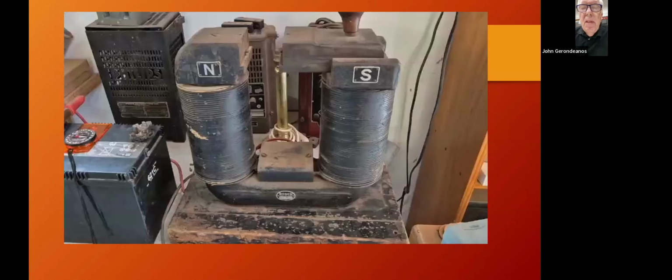And then the maximum amount of turns you can get on there with the thinnest amount of wire will build your best magnetizer. So the key steps to plan are, obviously, we define the requirements and we calculate the magnetomotive force. We're not going to do that. We're just going to take examples from real life, but if you wanted to, this is what you do. Calculate the magnetomotive force. It's the number of turns and the current through them.